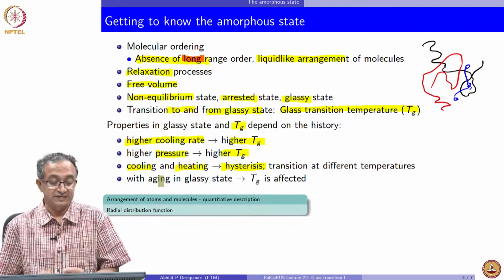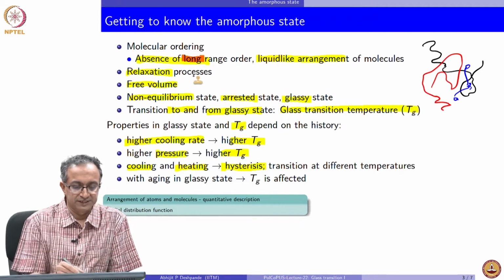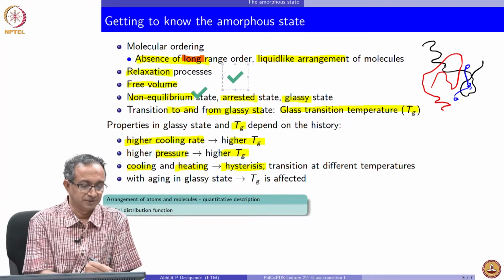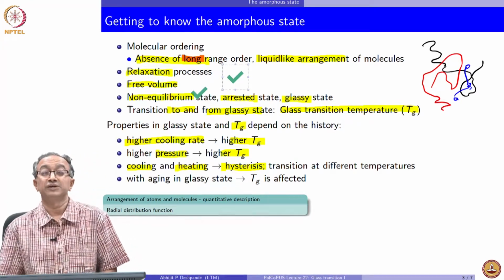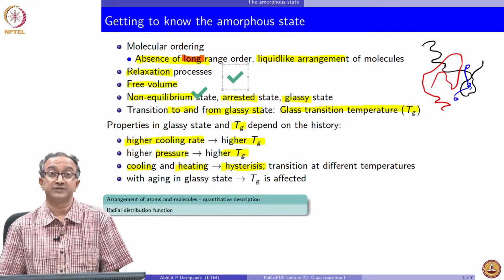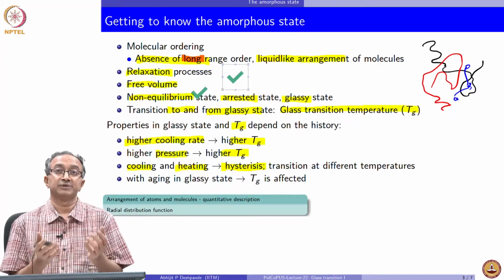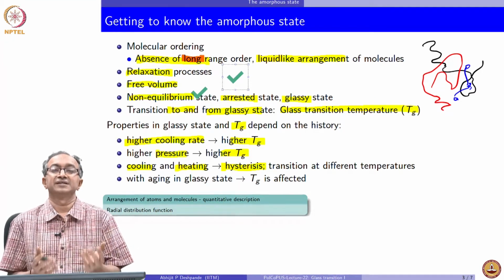And this is precisely what we meant earlier when we said that we have basically free volume and relaxation processes which are taking place in the material. So, because of this, when a sample is brought below the glass transition temperature and is in amorphous state, so for example, PET bottle which at room temperature or 35 degrees Celsius or 15 degrees Celsius is in the glassy state.